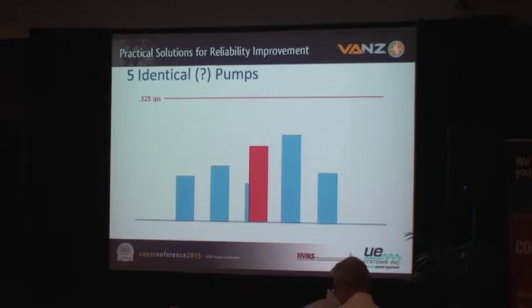I said, it's going to hit 0.325 inches per second when it continues to increase in the very near future. If you don't take it out of service and put the other pump in service, it's going to hit 0.325 for about that long. And then it's going to get really, really quiet because it's going to have come to a screeching halt. Okay, Bob, I'll send a guy down to do it.